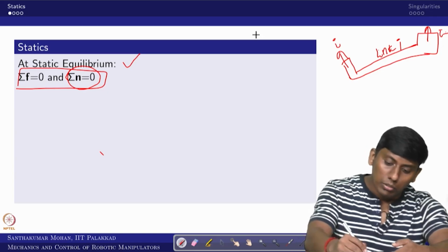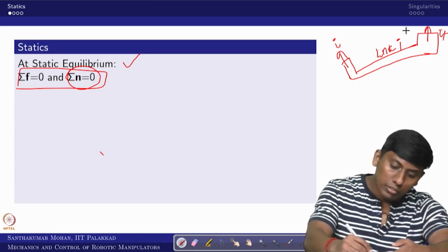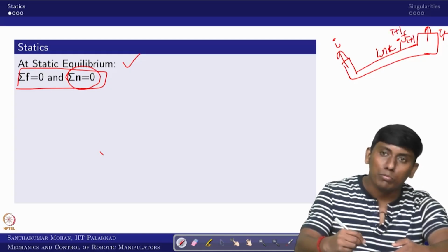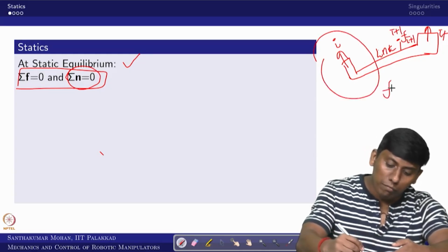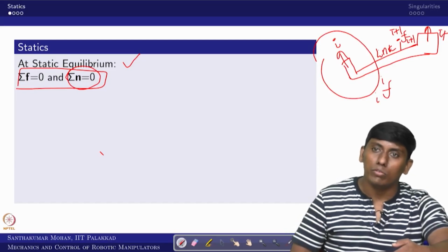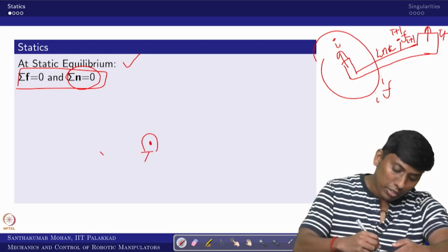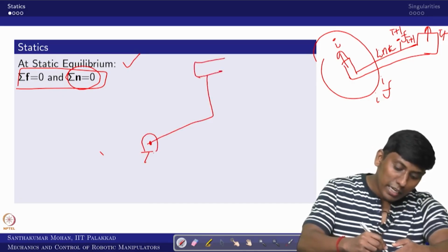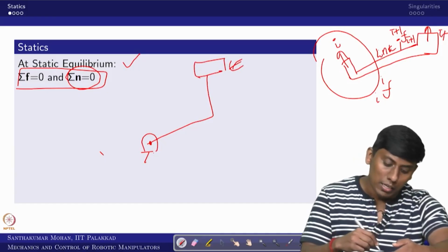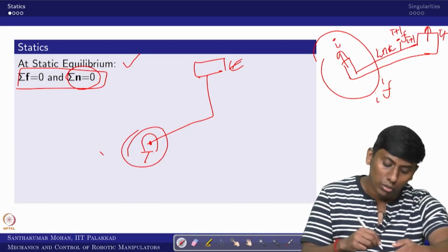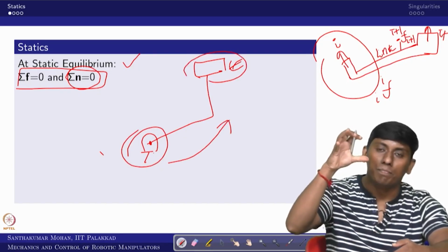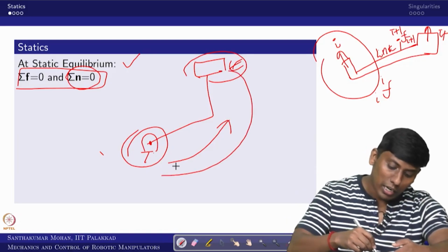Now if I have a force at i plus 1, can I get the force at i? In the sense, we are trying to come backward. Why is it backward? Because we are talking about the serial manipulator, the end is clearly known. Just as with velocity propagation from the base, where the base velocity and acceleration are known and we do a forward propagation, the end side, your task end, is known. So from there we are trying to come back.